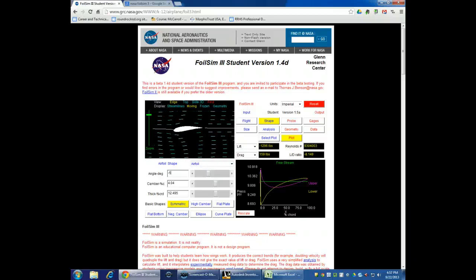But of course, you notice here again, I've created a lower pressure region higher than the upper pressure region. So even though this is angled downwards, I'm still getting a little bit of lift. My lift ratio is pretty small. And then if I keep going negative, taking this way, you see those go that way. And now again, I get the bad situation.